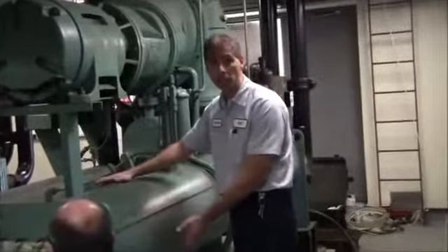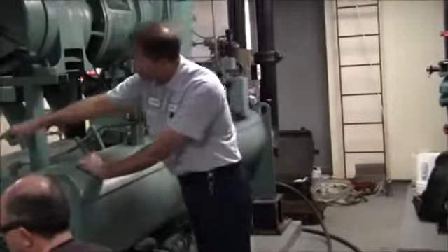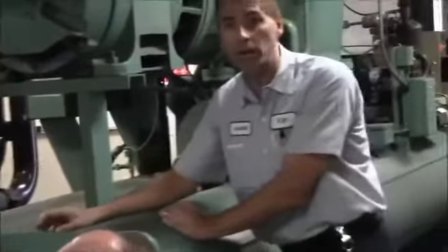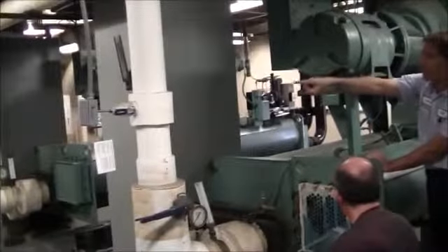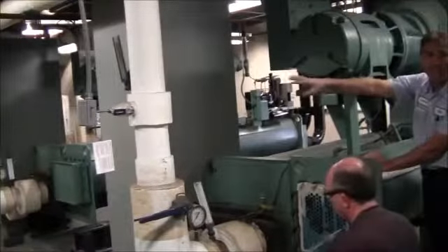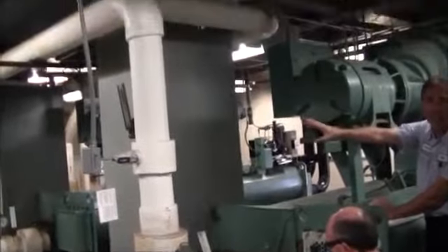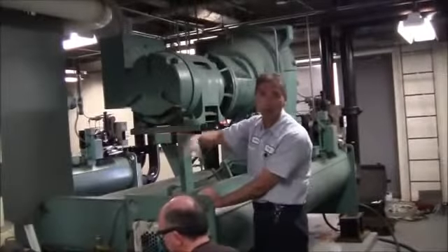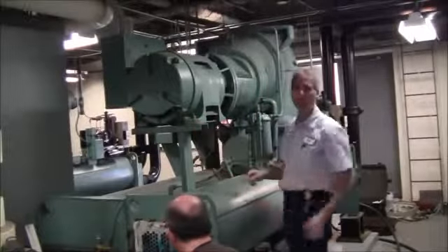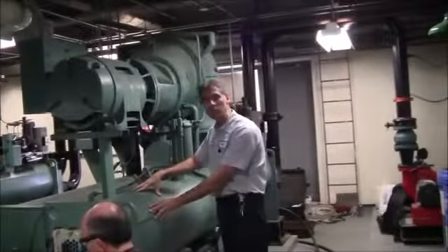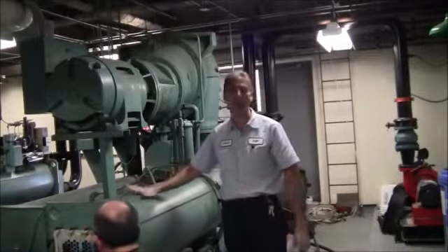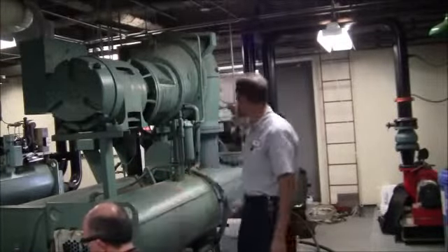There's no insulation around this shell. The evaporator, which is right over here, has insulation on it, keeping your water chilled. Also, you see your piping is insulated as well, maintaining that chilled loop, because you don't want to lose any heat out of it. You don't want that water to get warm at all or absorb heat, so you keep it insulated. The condensing section on the opposite hand, we don't mind rejecting some heat, so we don't insulate these pipes.